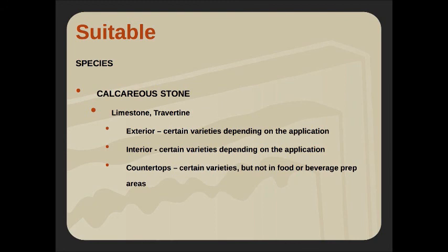Interior, again, it's doing the homework. Most of these are going to be fine, but am I going to put Indiana limestone on a lobby floor? Probably not. Just isn't quite as hard as we would like it to be. Will it hold up? Yes. Are you going to have wear marks in it after time? Yes. And is that what you want as an end user? Probably not. So, and then again, countertops. If we're going to use calcareous stones and countertops, we got to set that expectation early on. It might be fine for a vanity. It might be fine for a transaction top. It might be fine for the valet, but it may not be ideal at the bar, because we just know it's going to be etched inevitably.